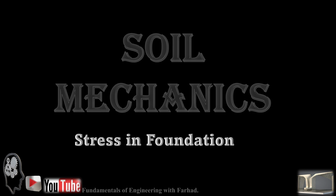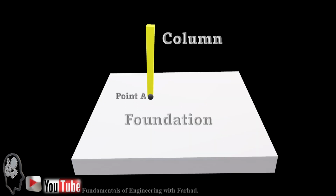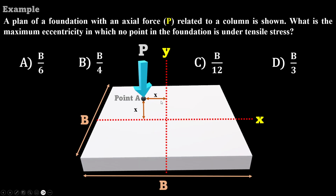Soil mechanics, stress in foundation. So we have a foundation and a column at point A which applies a force of P at this point. We have a plan of a foundation with an axial force of P applied at an eccentricity of x from the X and Y axes. We want to know what is the maximum eccentricity in which no point in the foundation is under tensile stress.